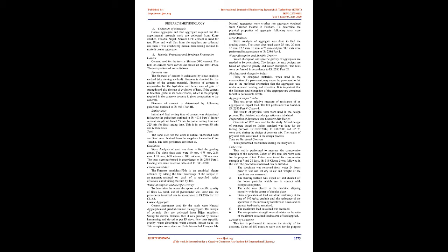Ceramic wastes have special properties, which can contribute positively in other areas of recycling. The study identifies physical properties of CTA as a partial or full replacement for natural coarse aggregate. Also, this study will help designers and planners to consider CTA as a good alternative to natural coarse aggregate, so they can manage the ceramic tile waste byproduct.